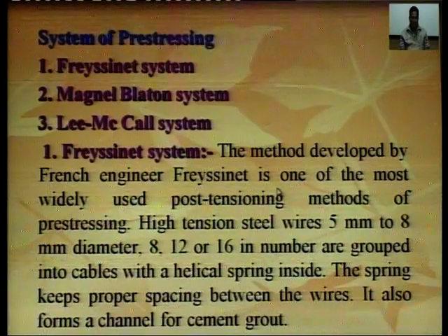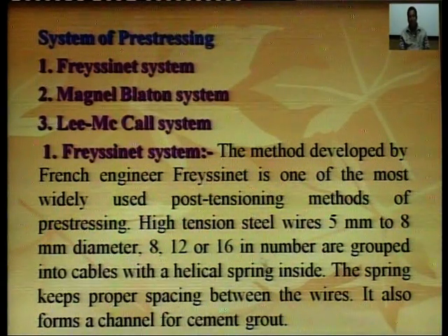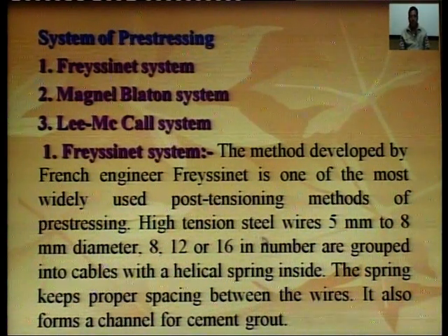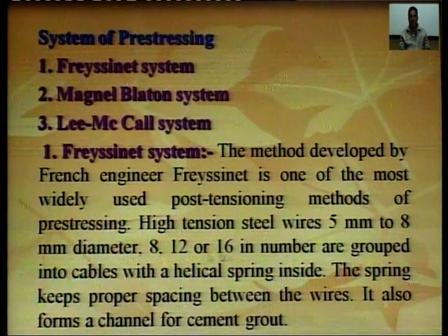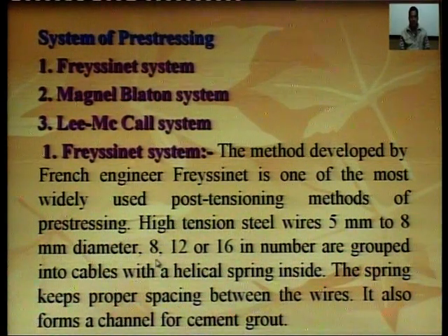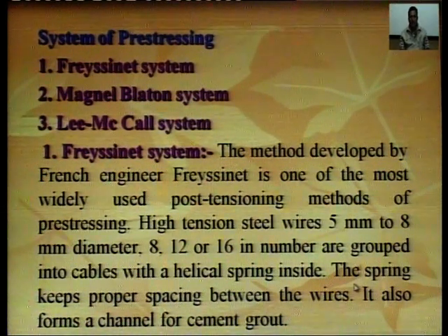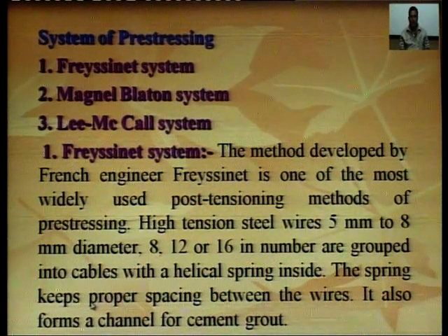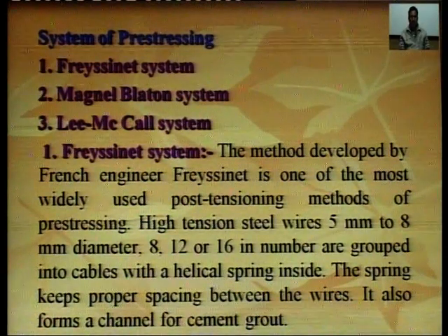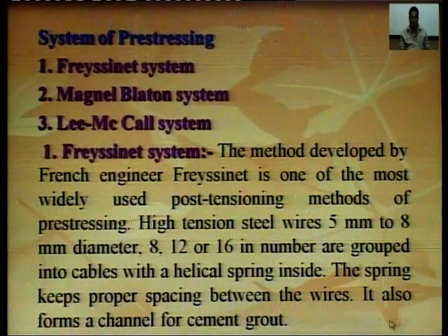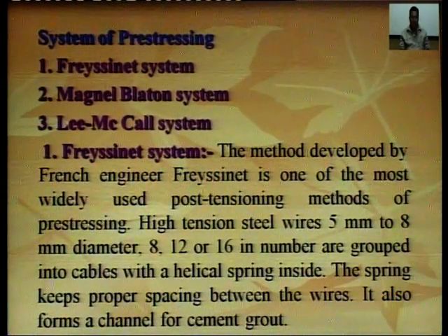Engineer Freyssinet developed this method, and it is used for the post-tensioning method. High tension steel wires of 5 mm to 8 mm diameter, 8, 12 or 16 in number, are grouped into a cable with a helical spring inside. The spring keeps proper spacing between the wires. It also forms a channel for cement grout.